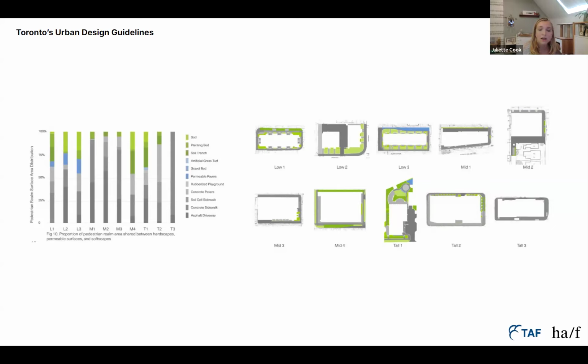And so it could also be surmised that low-rise projects have reduced areas of hardscape due to the fact that they may only need short paths to entrance doors or stairs, while mid-rise and tall building projects have requirements for increased areas of hardscape per current accessibility guidelines and to connect with immediately adjacent surfaces in the more developed city core. Impermeable hardscape assemblies not only have fewer environmental co-benefits, but also significantly higher embodied carbon intensities than do softscape and permeable surface types.